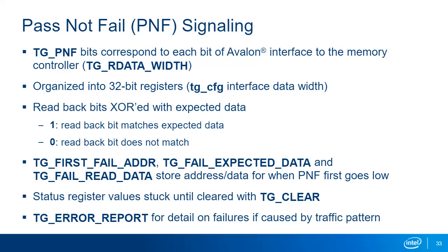TG PNF bits and these status registers are sticky, so you won't miss a failure if subsequent tests on that bit pass. Write to the TG clear register to clear just the TG PNF bits or to clear all failure status.